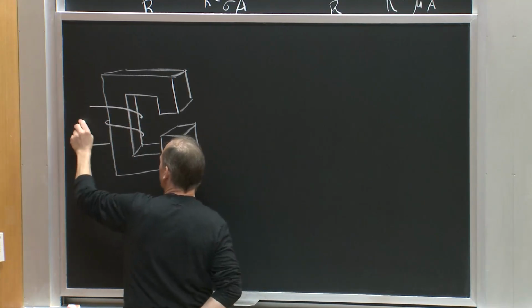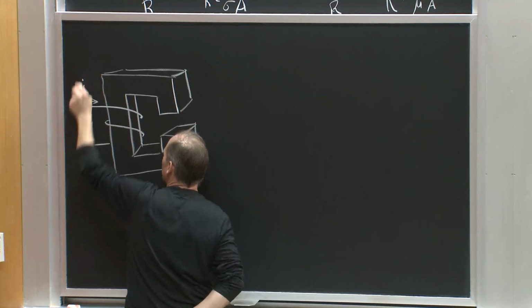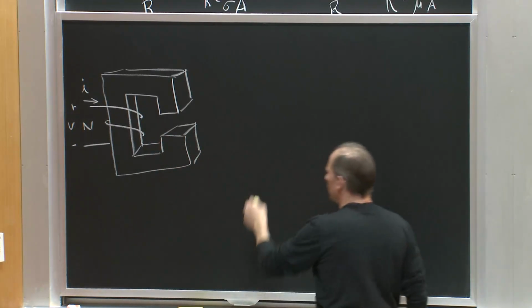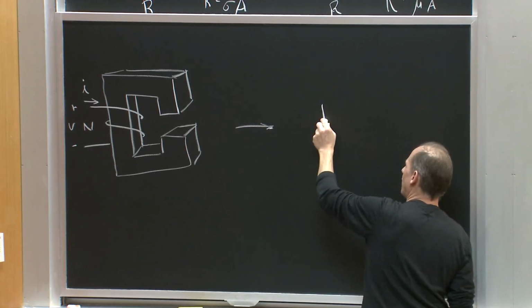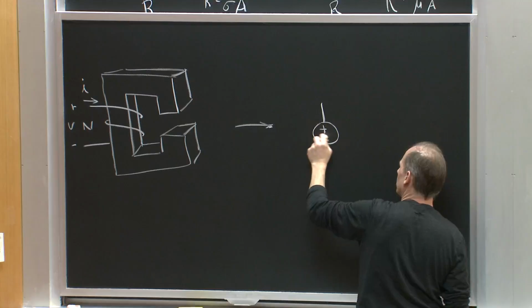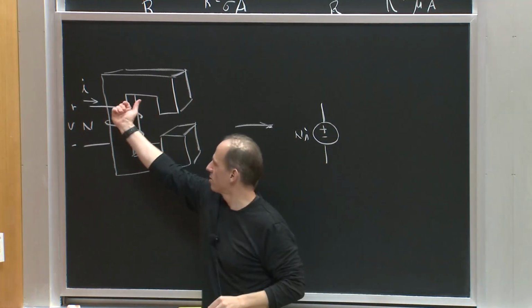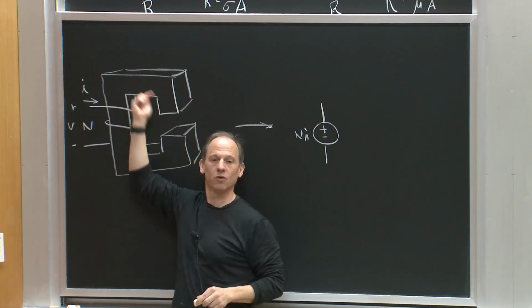So we would have N turns of current I, and we get voltage V. And we said my magnetic circuit model would be Ni trying to drive flux in the core, and a positive current by the right-hand rule is trying to throw flux clockwise around this core.